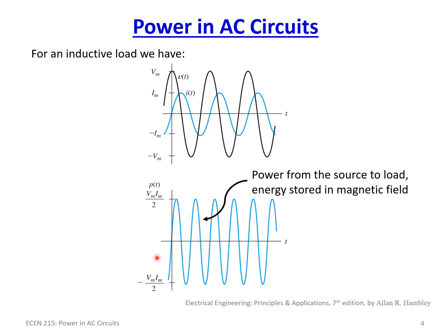So remember from early in the semester when we talked about positive power and negative power, positive power is where the element is absorbing power from the circuit, and negative power is where the element is returning power or sourcing energy back to the circuit. Here, the energy is being consumed by the inductor, being absorbed, and is storing the energy in the magnetic field. Here, that energy is being released back into the circuit, being supplied into the circuit, different phrases of the same thing. So it's being released back into the circuit, and hence it's negative power.